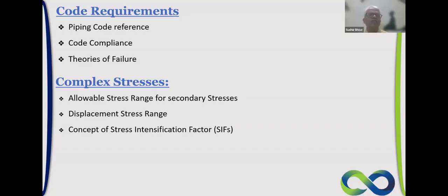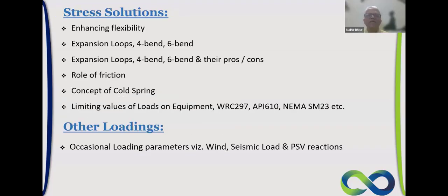We will also understand the complex stresses in terms of the secondary stresses which are generated due to temperature, and the concept of the stress intensification factor, which is more important from the point of view of the analysis and how it affects the entire analysis. Then we will also study the different solutions. Once we understand the problems in the system from the generation or passing of the temperature, we find those problems and then attack them to resolve them and meet the code requirements.